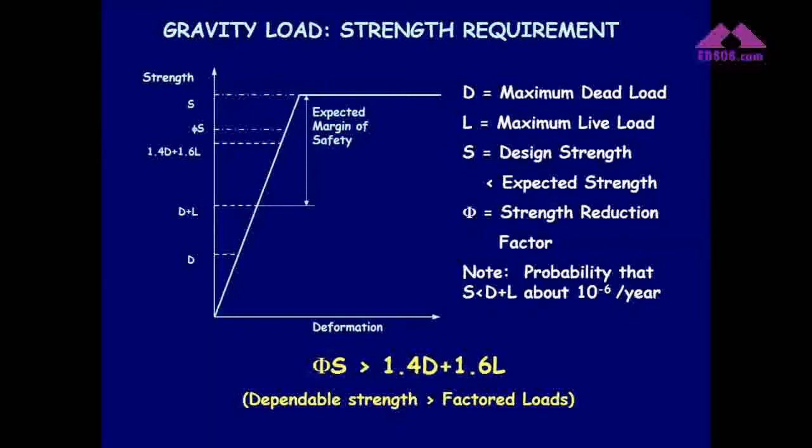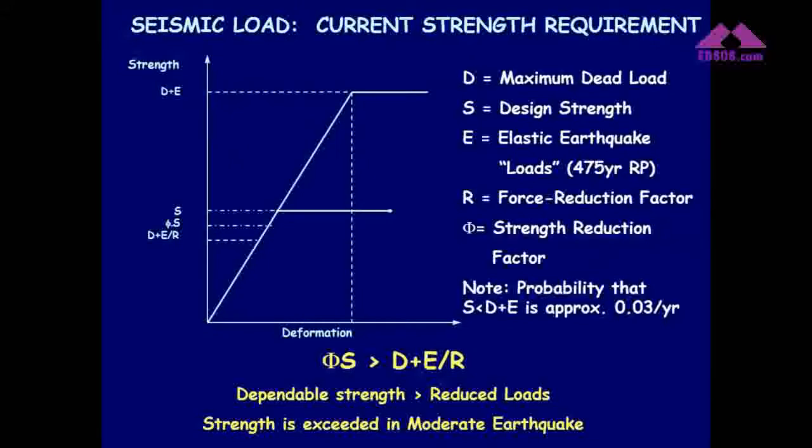But not only this level, we also have some strength reduction factors. For example, we say that we order concrete to a level of concrete quality, let's say 30 megapascals compressive strength. What we do during the design process, we reduce this compressive strength 1.5 times more. So we have a real large margin of safety for gravity loads. But for earthquake loads, this is not the case.